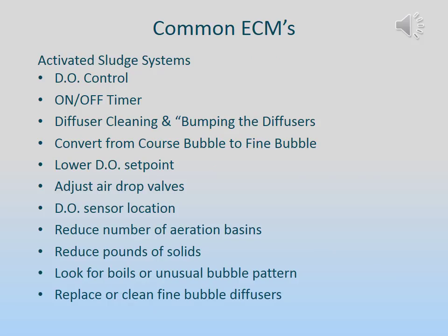When it comes to activated sludge systems, ECM options for DO control include on and off timer control for blowers or air drop valves, diffuser cleaning and bumping the diffusers, converting from coarse bubble to fine bubble diffusers, lowering the DO set point, adjusting the air drop valves.